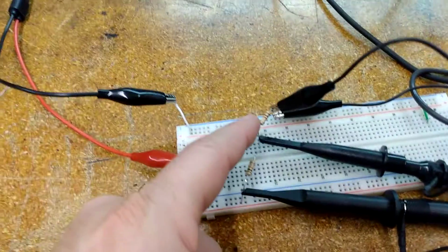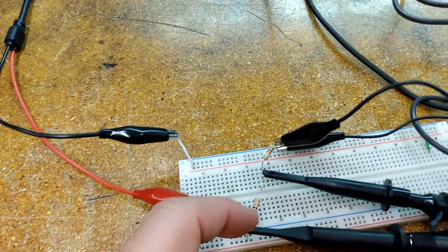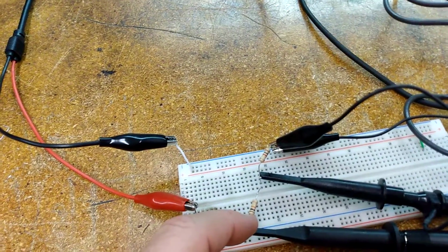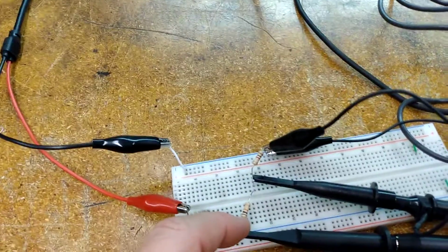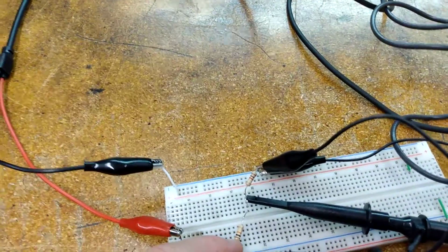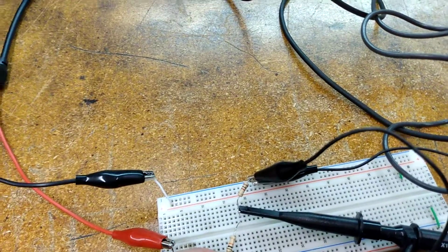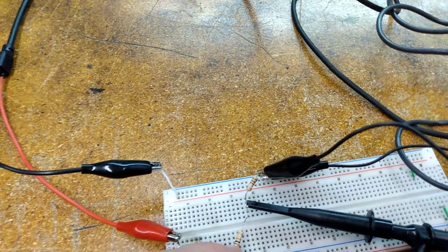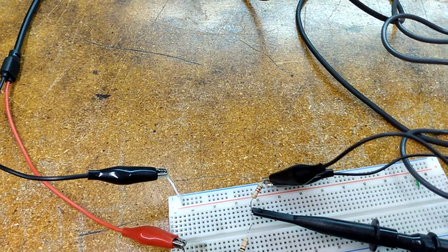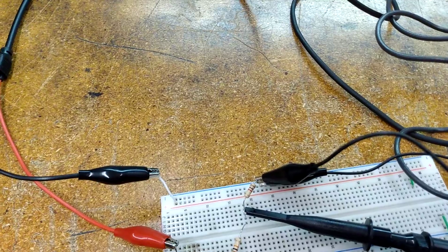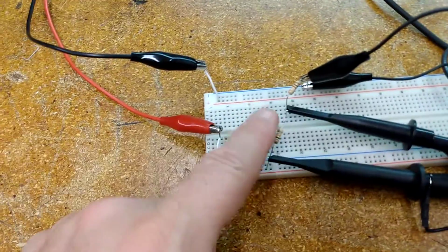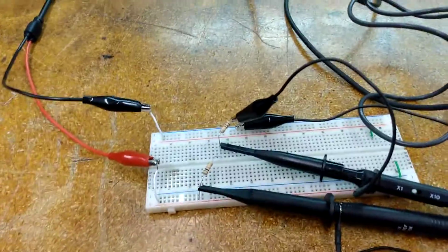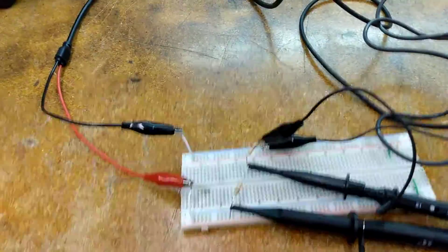Now that's the voltage drop on this one, and obviously, as we saw earlier, you're going to see the difference of that voltage over here. So if we were at 0.37, then what we're going to see is probably 7.6, or 7.53, I guess, would be our difference over here. So in terms of our peak-to-peak voltage, we're able to verify the same exact voltage drop with Kirchhoff's law.